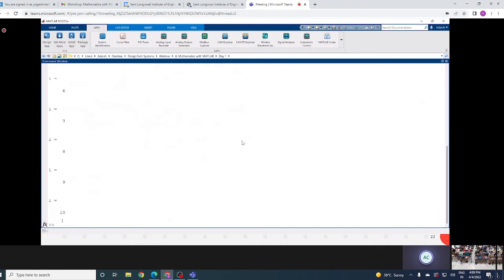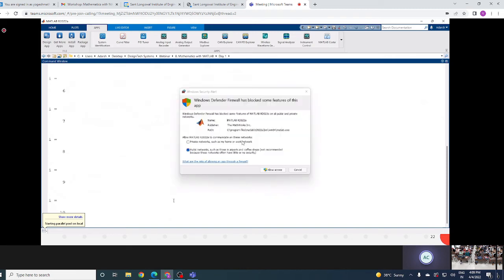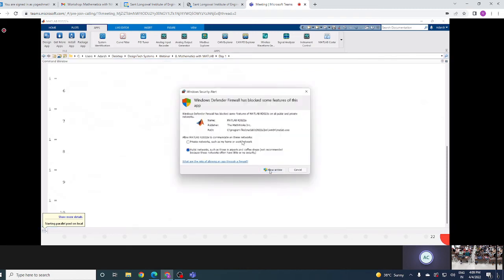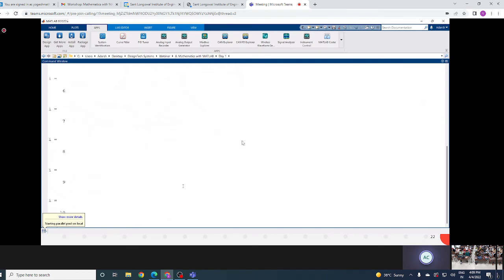But if I want to turn on my parallel processor, you can get this on your desktop application. If you click here on this, then you can start a parallel tool. This is generally required when you are dealing with very big or larger data where your computation can take a lot of time. For example, training your artificial intelligence network, like a deep learning network. For that kind of application, it is very important. It will take a little bit of time initially for starting, around 1 minute.